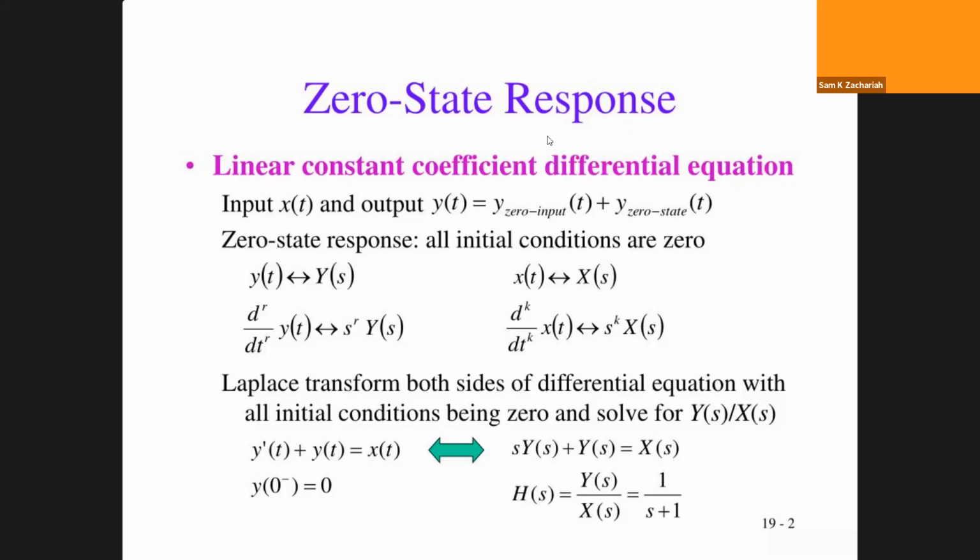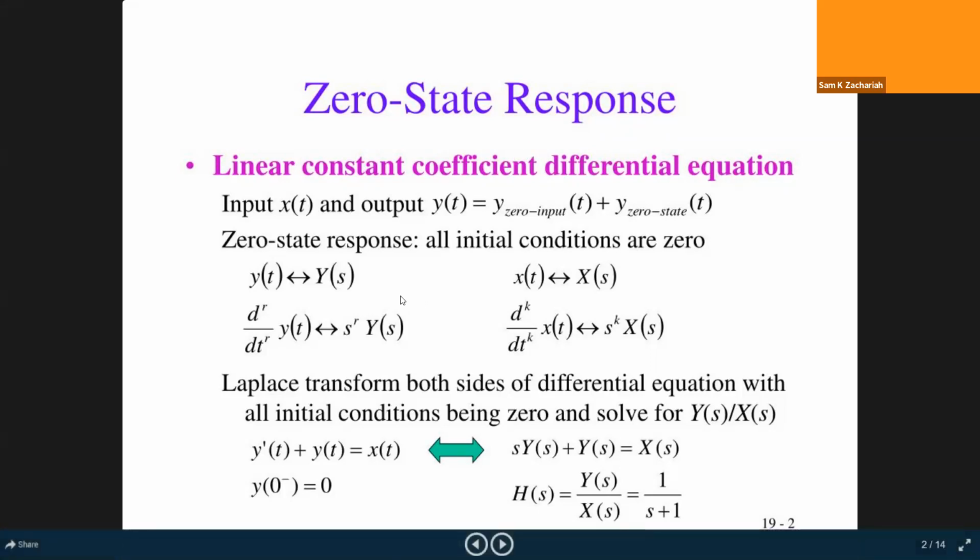So under that condition, what will happen? They define the transfer function, but in general, the system output y(t) is due to two parts: one part due to zero input response, another is zero state response. Now we are considering only zero state response. All our discussions are with zero state only, that is, our dynamical system is starting from ideal rest.